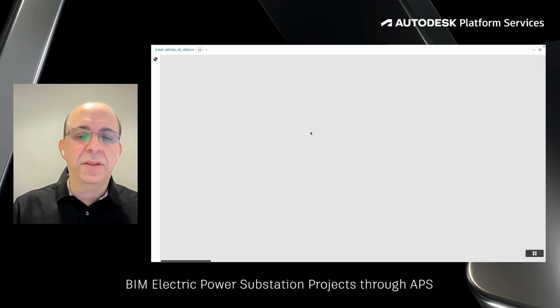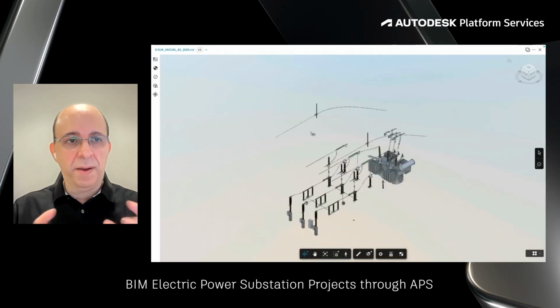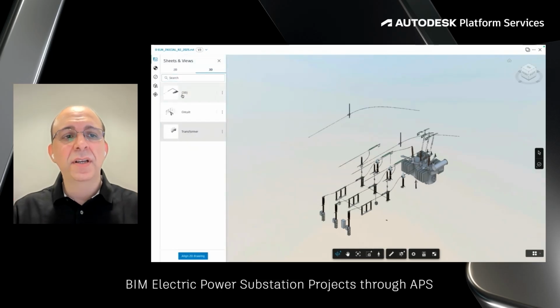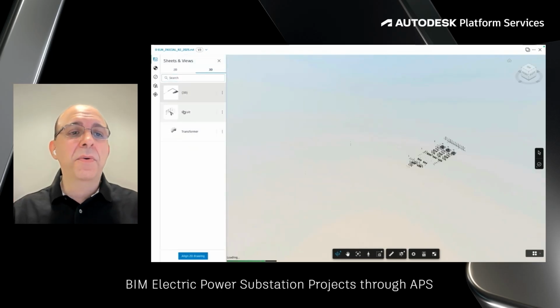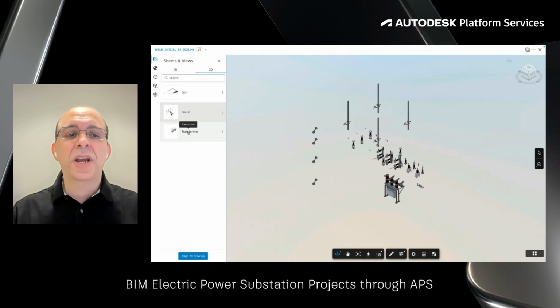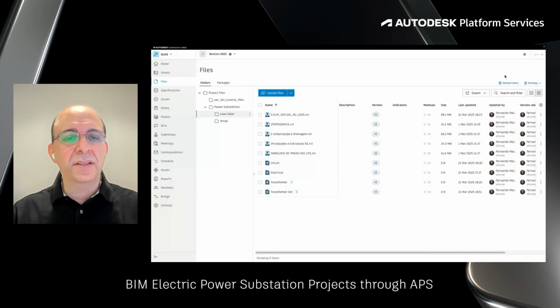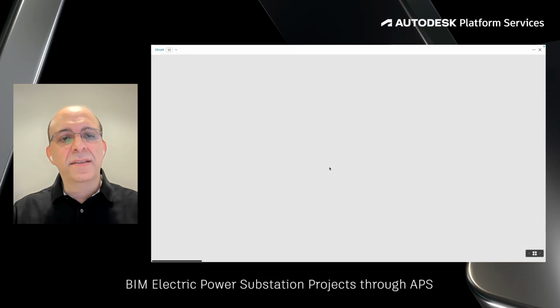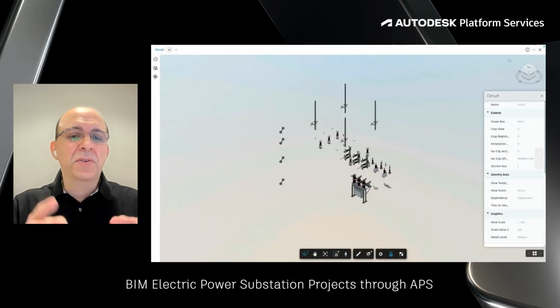We're going to show a little bit of examples here. So I'm inside Autodesk Construction Cloud. I published this Revit design. It's just a section. And then I'm going to create a data exchange out of that model, right? So in this example, I'm creating a data exchange here in this view, right? And this is the data exchange we created. It's going to be a subsection of the whole 3D model.